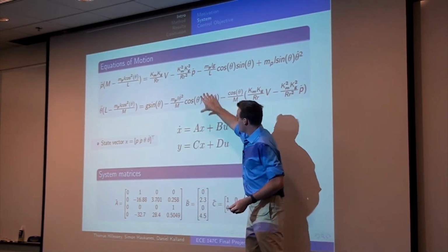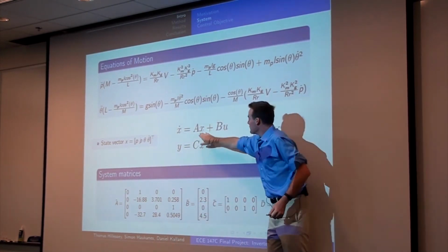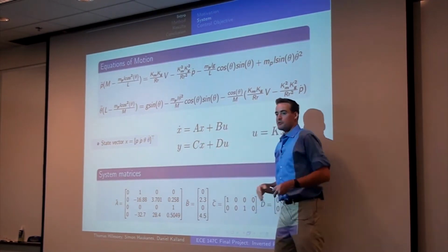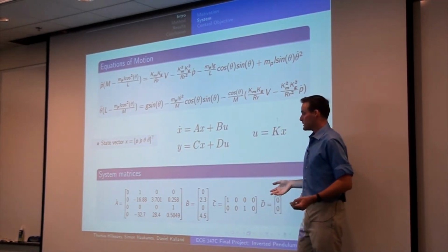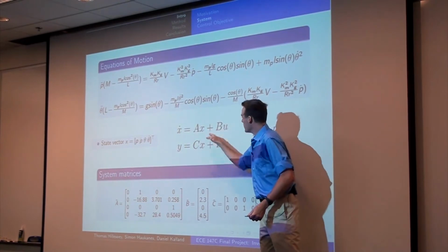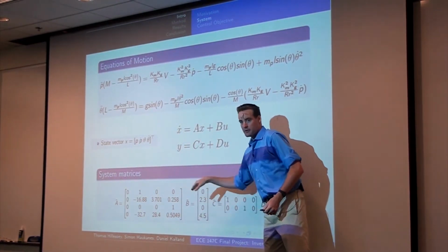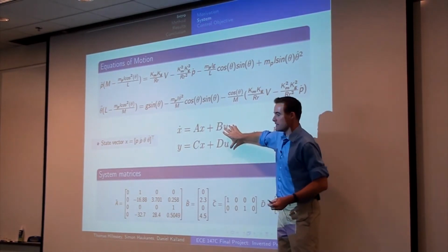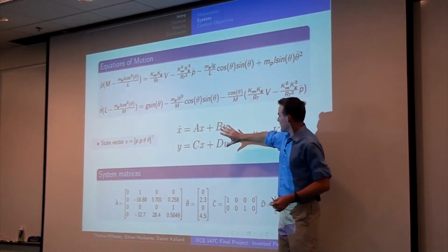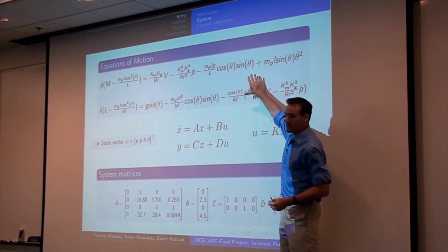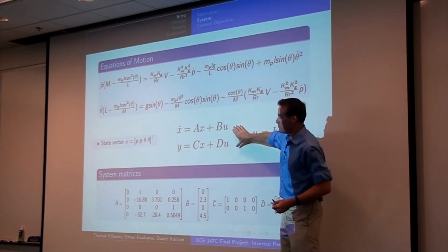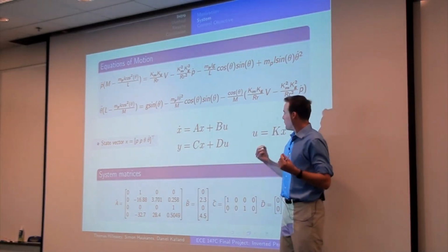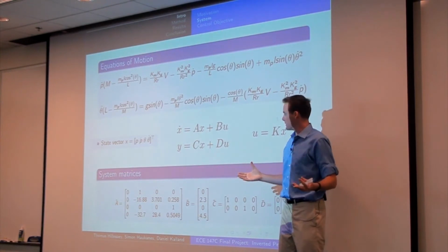Once they've done this technique called linearization, these are just constant matrices, and the students use another technique that we teach them called system identification for figuring out what exactly are the numeric values of these 4 matrices. This is great news for the students because they have boiled this big complicated system down into a very simple canonical form that describes the motion of their system.